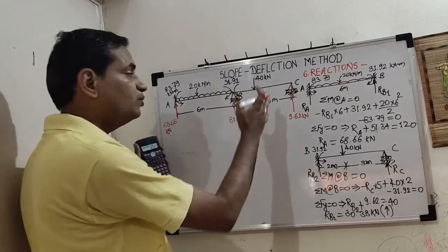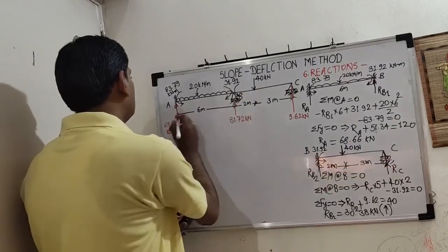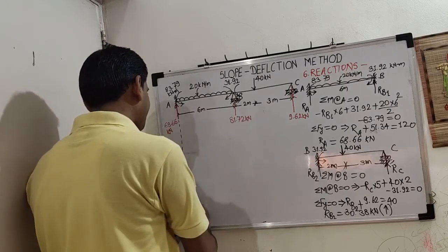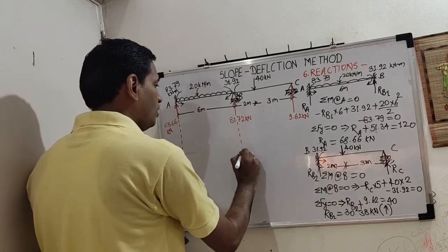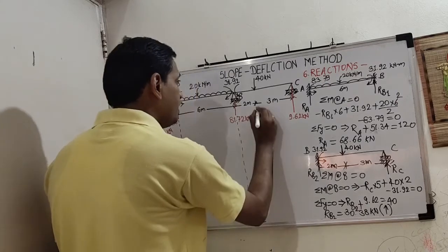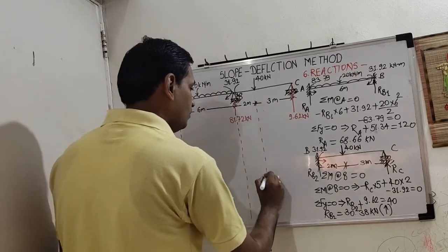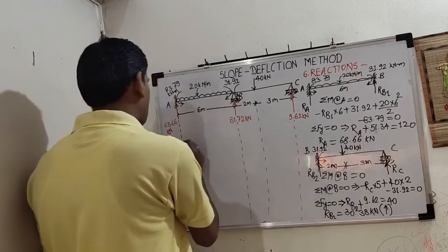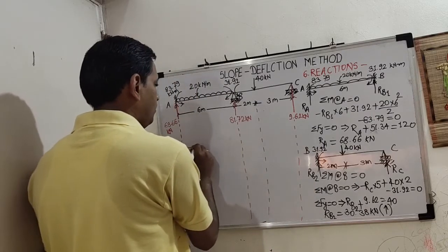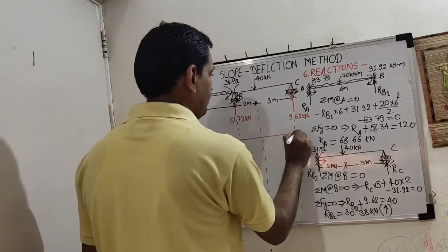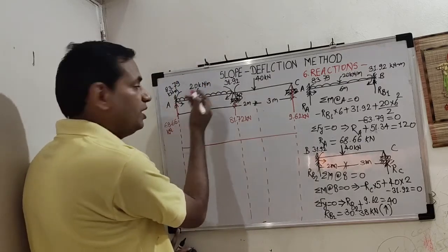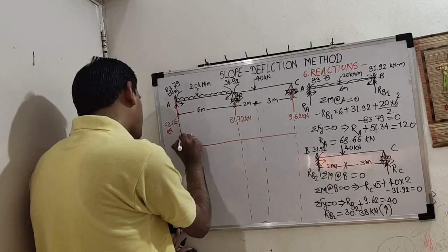So now we can draw the shear force diagram because we have got all the reactions. External loading also we will have to consider. So let us take first of all these projections and draw the appropriate shear force diagram. So shear force on A is the reaction on A, 68.66 approximately.